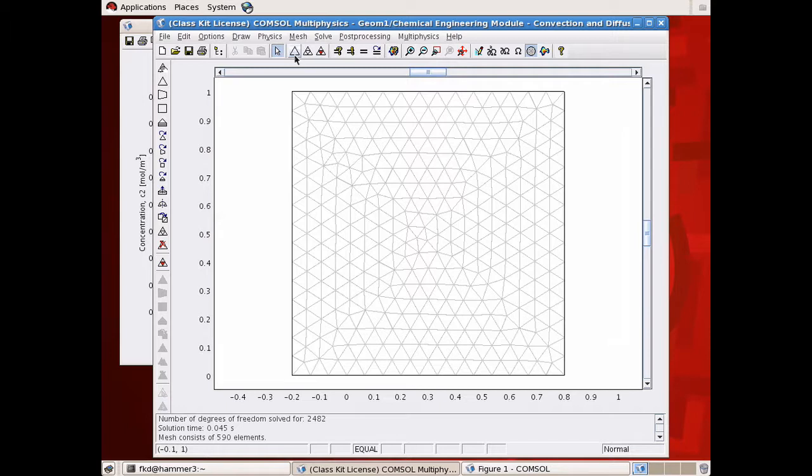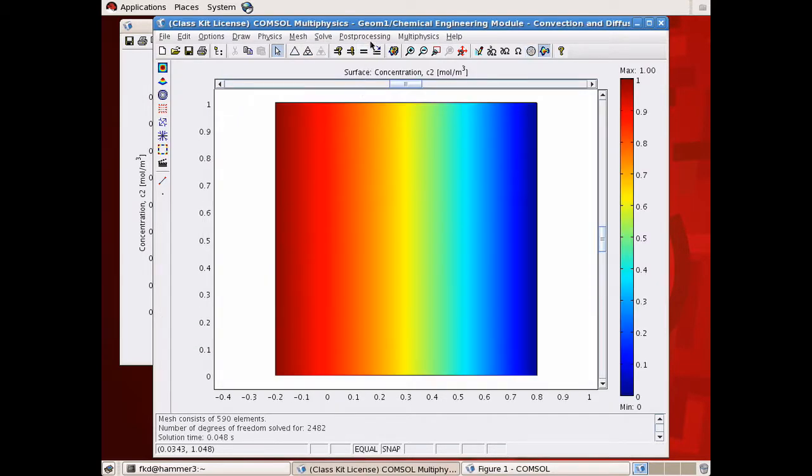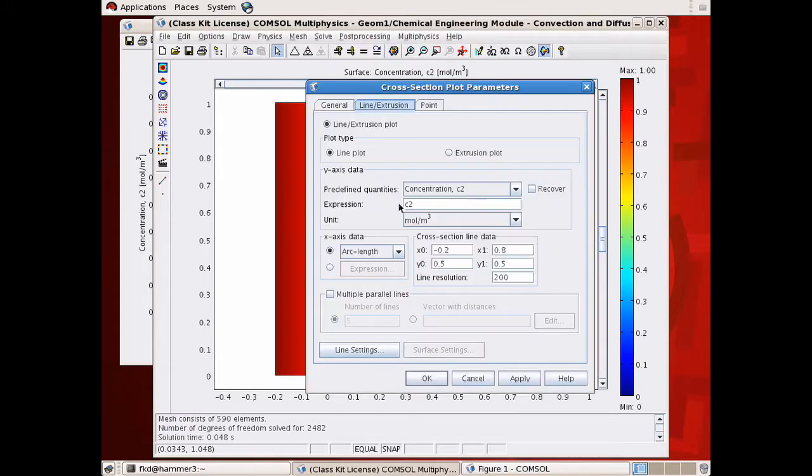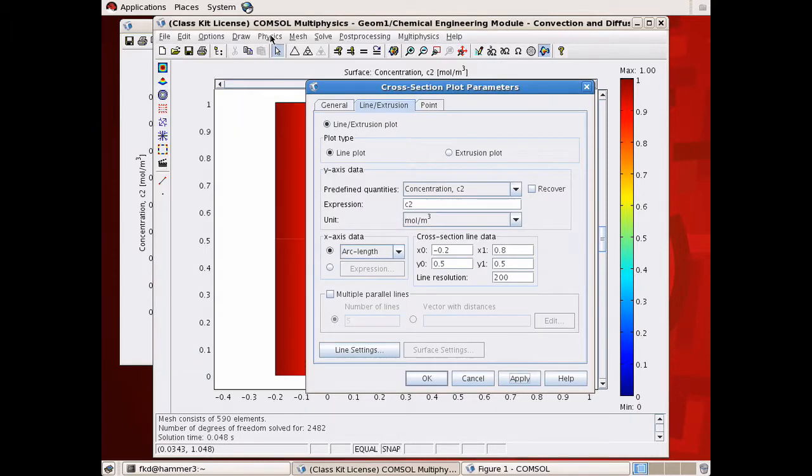So it looks like the mesh size is certainly less than a tenth. Looks like there's 20 elements on one side to me. And so the Peclet number should be okay. So we should get a result that makes some sense, hopefully. See if we can run this. Is this on the right parameter? Yeah. And you see, instead of this two-part component where we had two elements in our system before, now it's completely curved.